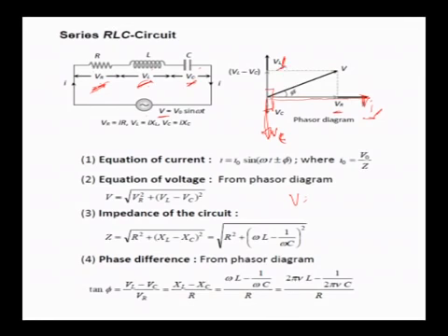Then in that case, the expression for the current induced is I equals I naught sin(omega t plus or minus phi). The maximum current is voltage divided by impedance. This is the formula to be remembered, because in the normal case of series connection of resistors or any other components, net voltage will always be the sum of the voltages applied across the individual components. But in this case, it is the vector sum, which is V equals root of VR square plus (VL minus VC) whole square.